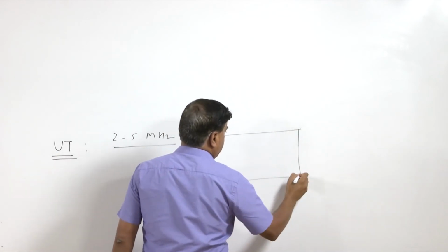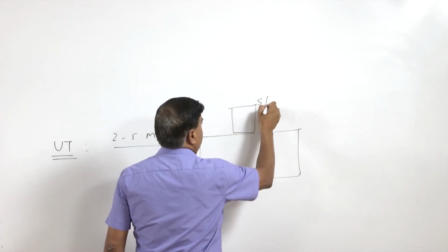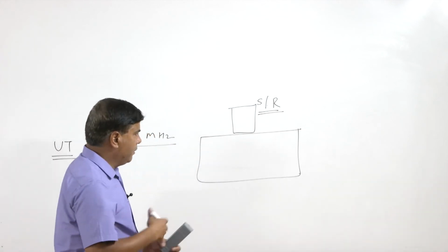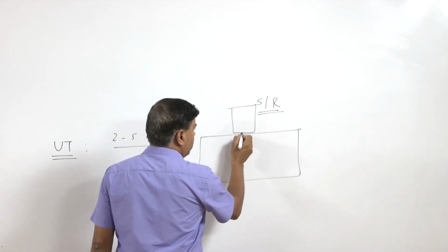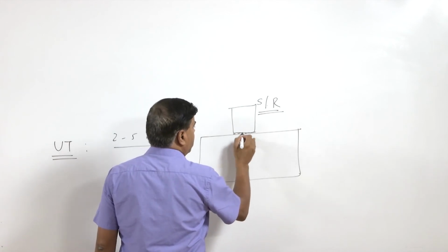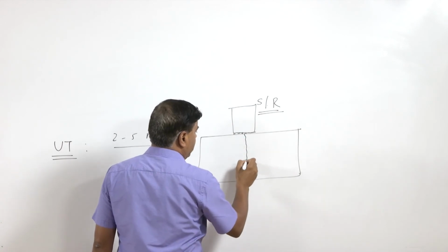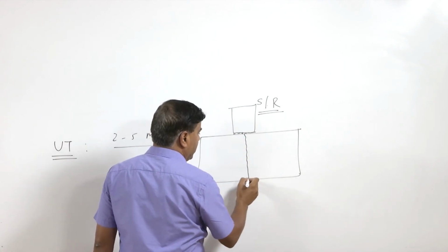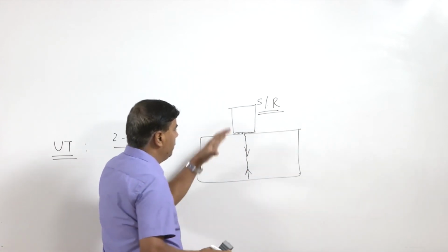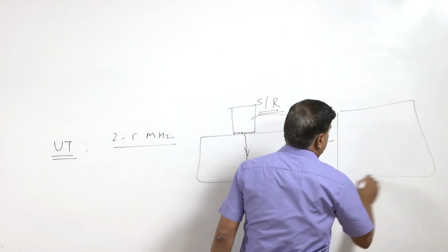So, in that case, say this is the probe which is working as both the source and the receiver of the ultrasonic vibrations. Here the vibrations are transmitted into the component through the coupler, the first wave will be reflecting back, and then it will reach the other end and reflect back. So sending and reflecting back both happen, and this is recorded and seen on the oscilloscope.